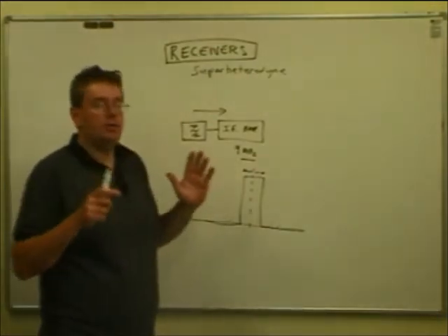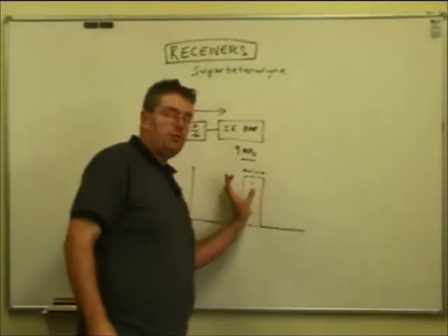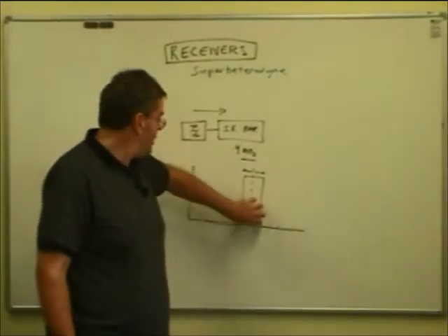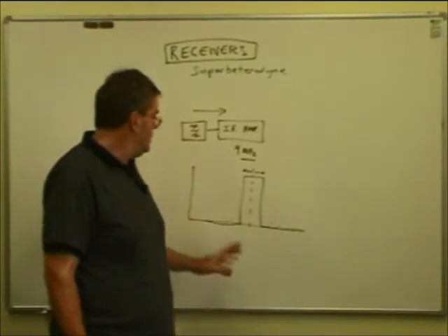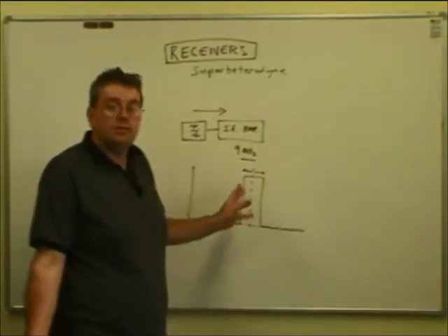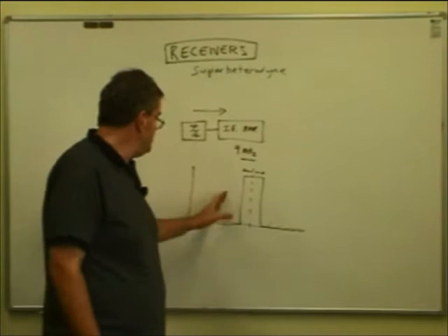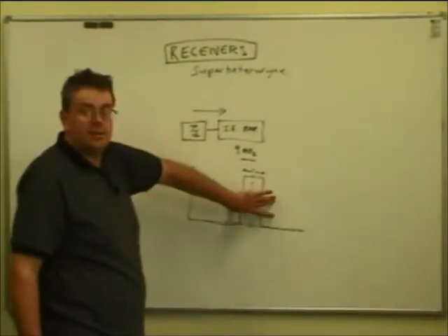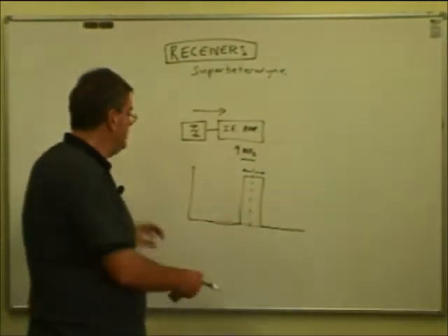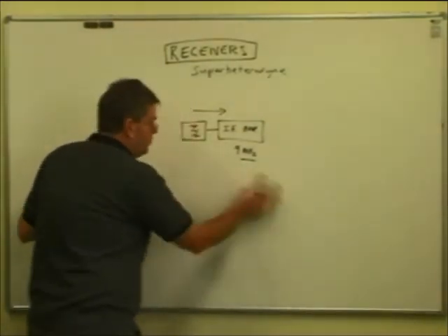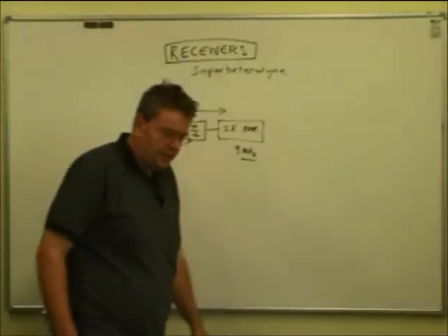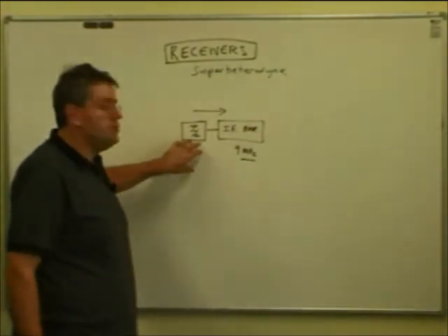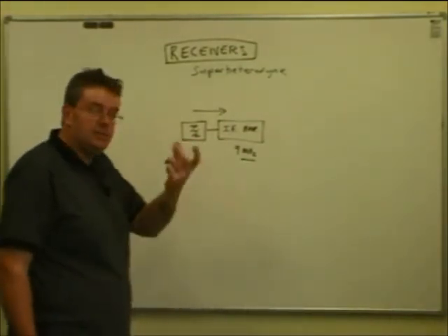It's just like a window on the radio spectrum, if you like, that's just as wide as we want it to be. Now, if it's a single sideband signal, only about 2.5 kilohertz, because that's all we want to get through there. That's all we tend to transmit when we use SSB, like we discussed with modulation. For frequency modulation, that would be wider to pass the FM carrier that's been wobbled around in there. So we put a filter in front of there. We talked about filters back in resonance, and we showed you a crystal filter or two. We'll show a real receiver in a little while. This is generally done with crystal units in a little package.